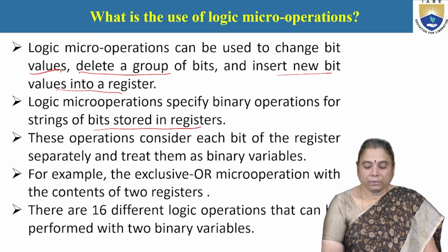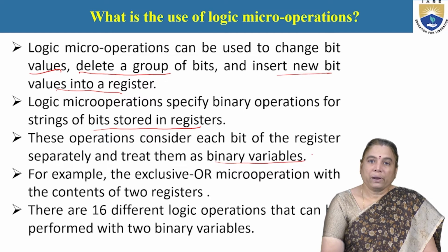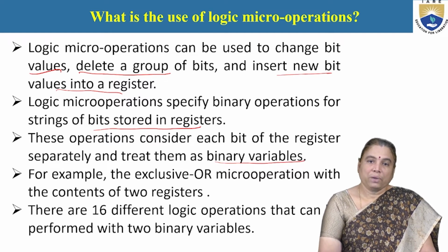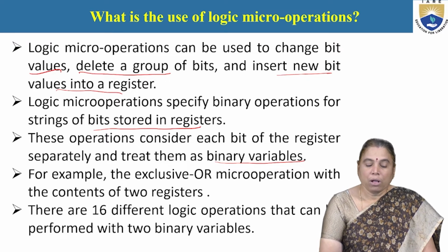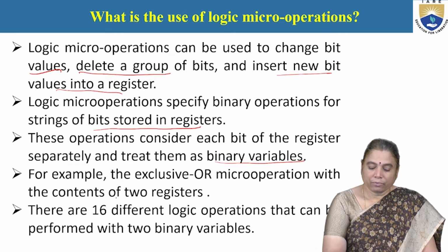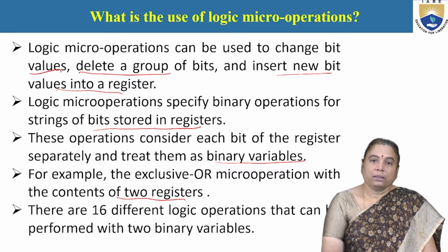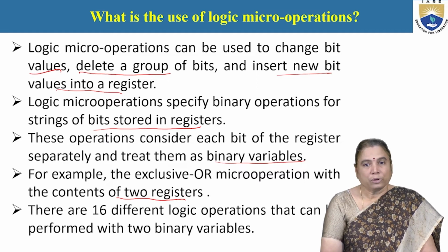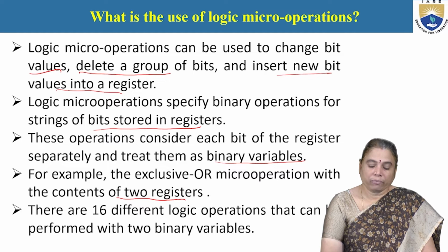These operations consider each bit of the register separately and treat them as binary variables. A single bit can be extracted from the register and the logical micro operations applied. For example, the exclusive OR operation can be performed on the respective bits of two registers.